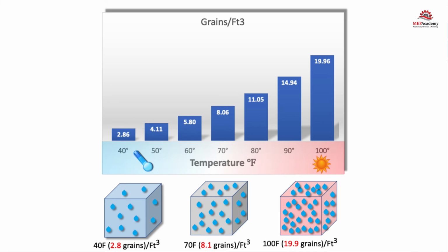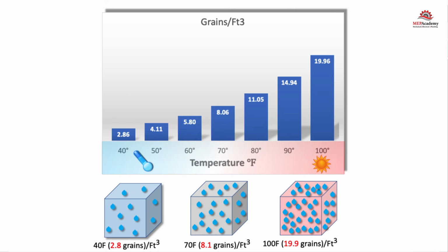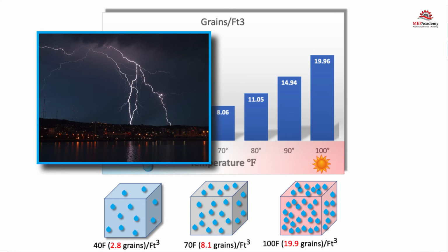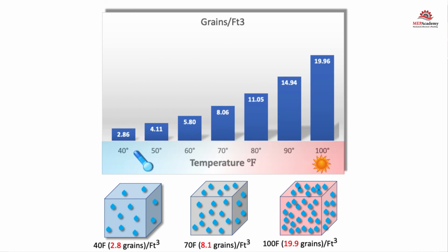Humidification is the process of adding moisture to the air to improve health and comfort, avoid high static conditions, and protect processes or products like museum paintings. Understanding psychrometrics, we know that when cold air is heated, the relative humidity drops and the air feels dry.